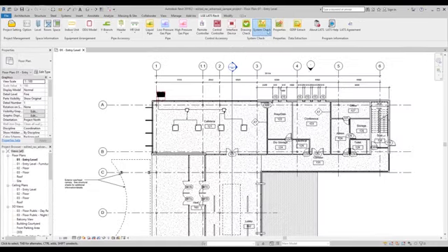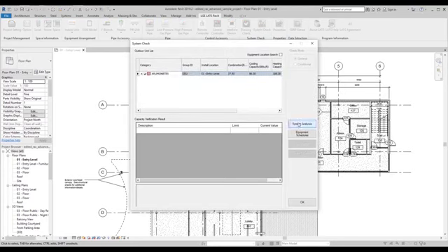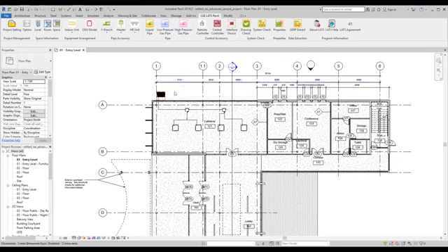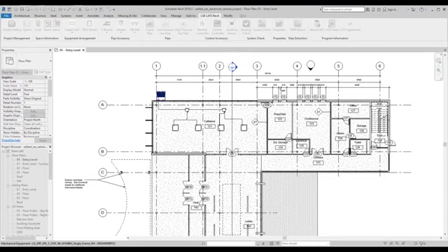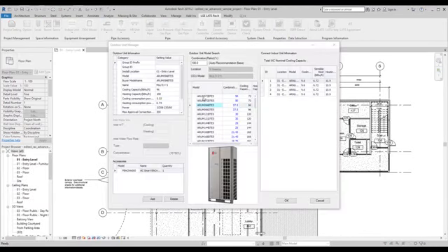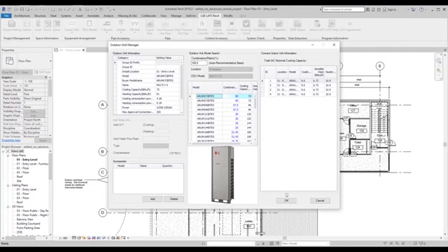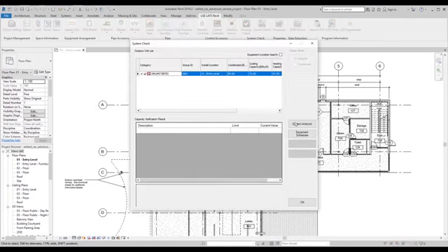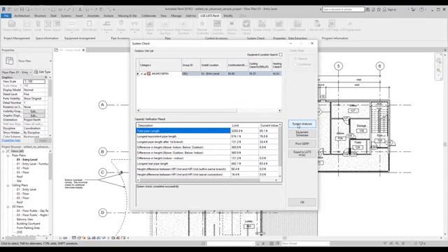Click System Analysis to calculate values for additional refrigerant, difference in height, and pipe lengths. If the results are highlighted in orange, you will have to redraw or change erroneous connections. Perform the system analysis again, and now you should get a message that the system check was completed successfully.